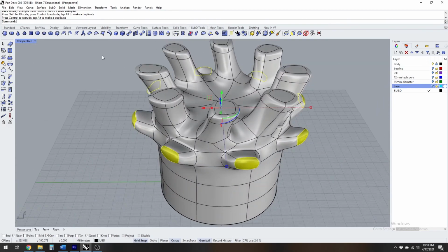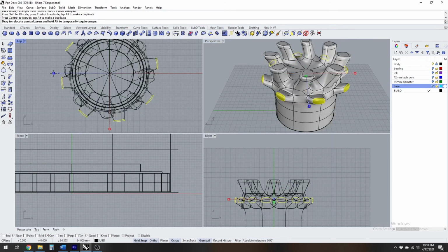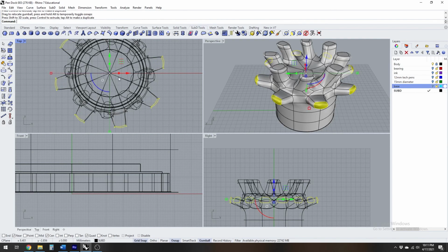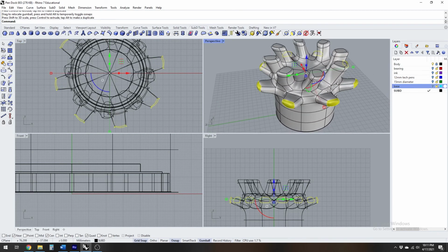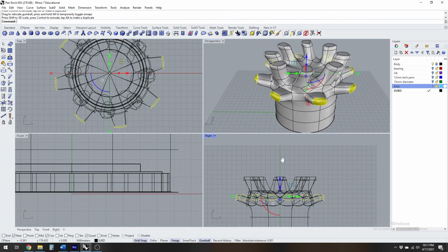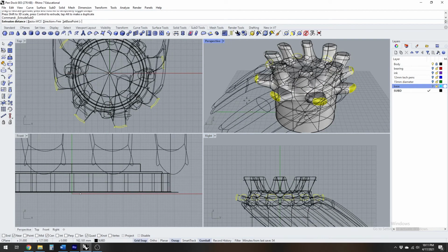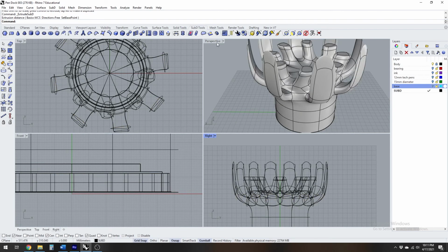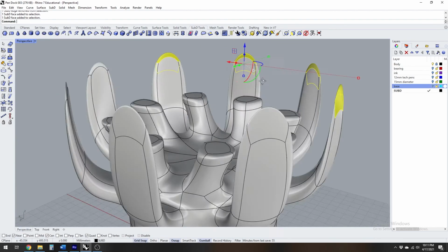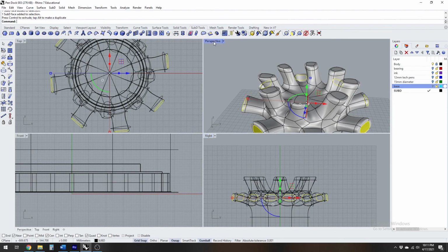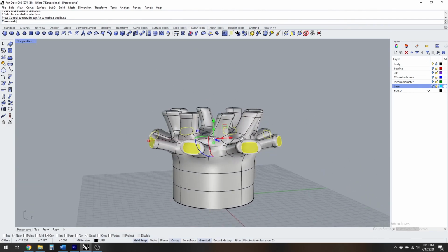Something that I find is a real efficiency builder in a model like this is understanding exactly what your selections do to how slow you move. So you'll see one thing that I'm constantly doing is, whenever possible, when I have edges or faces selected that I'm trying to transform, I try to do as much of that as possible while I'm there. Notice I moved from the scale and extrusion back into the second extrusion, and then now again I have to go back in and do manual selecting. That's the most time-consuming part of this process: just the manual selection in order to control 8 separate nodes.